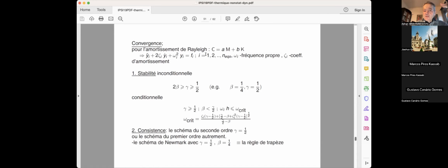We turn this whole system with Rayleigh damping into this modal equation, where you separate the dependency, so you can turn this into n independent vibration modes, where these are so-called modal coordinates that are fully uncoupled given this type of damping. So instead of mass, you have 1. This is the way you normalize these eigenvectors, and then instead of the stiffness, you have omega_i squared.